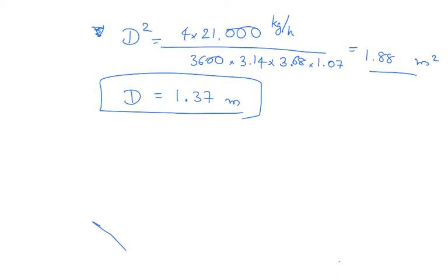So think about a yardstick and maybe 1.5 yardstick wide column, on circular diameter, and then how will you space the 2 trays? 2 feet is roughly about correct. Okay. So you see how you can design the columns this way?